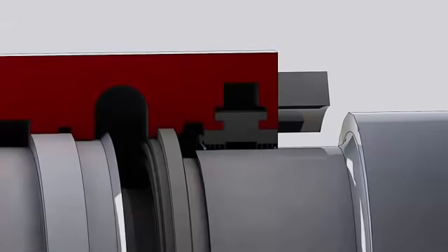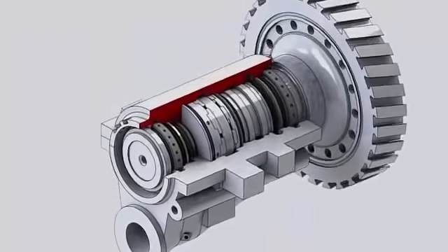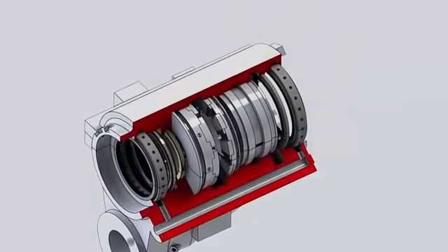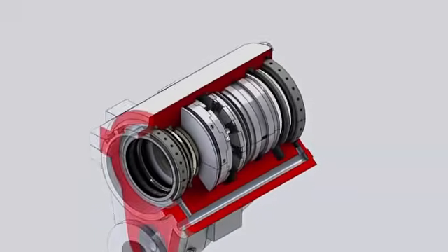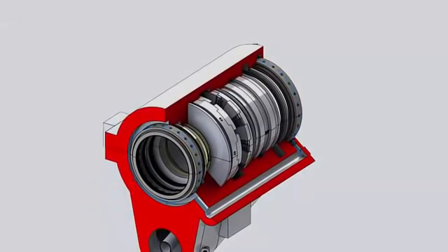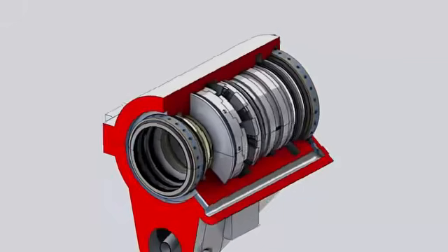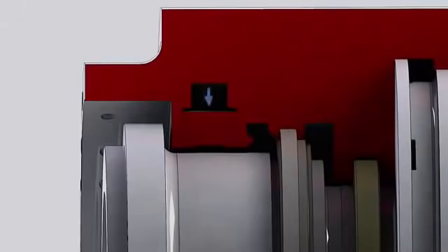Seals are assembled so that a small clearance exists between the seals and the shaft. The sealing airflow from the cooling and sealing system passes through the axial tube machined at the right side of the housing and is admitted to the labyrinth seals through 2 ports to annular spaces surrounding the seals. Between the 2 rows of seal teeth, sealing air is admitted through multiple radial holes to stop oil from spreading along the shaft.